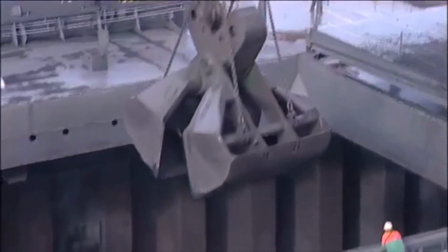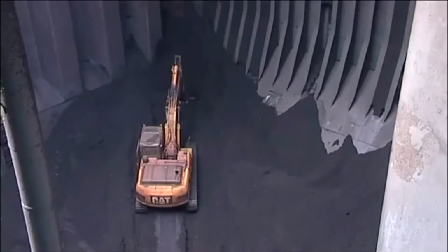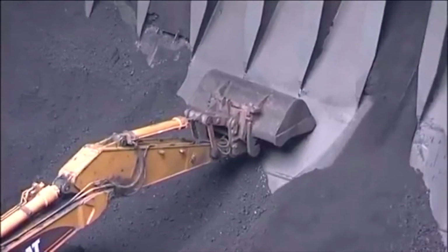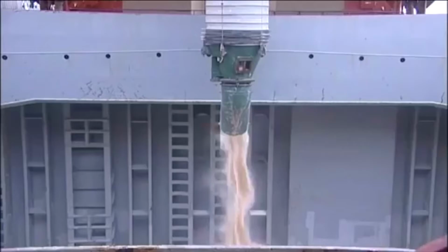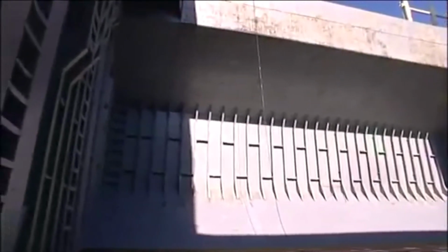During both loading and discharge, mechanical equipment may also damage the ship's structure. Whilst discharging, the use of grabs or hydraulic excavators can cause damage to the hold structure or its protective coatings. And during loading, it is the terminal's responsibility to alert the master to any individual grab loads or pours that are large or heavy, where there could be the risk of a high-impact drop. These could potentially damage hopper sides and tank top structures or stress the ship's hull.